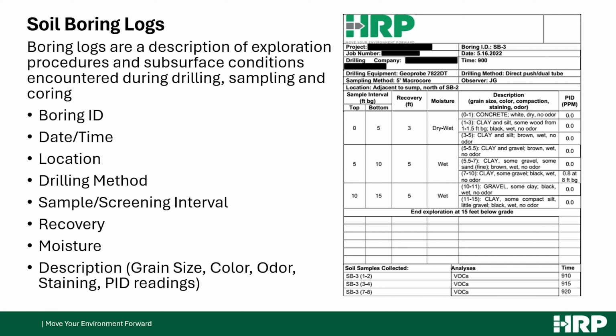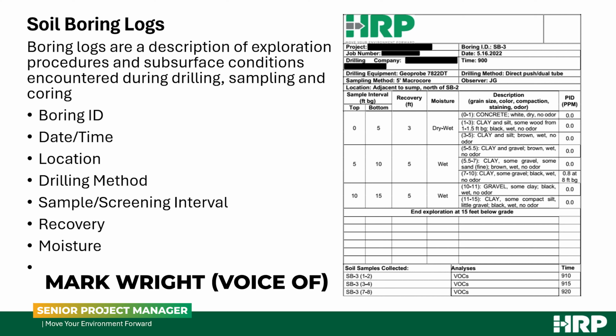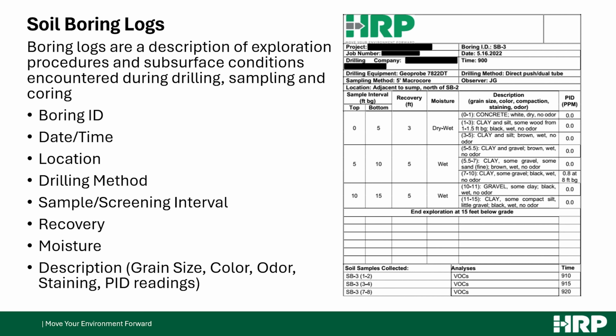I think one thing to build on that, Chris, when you are doing your soil logging, you should be making notes in addition to the description. If it is the same material that you see in SB1, if you see it again in SB3, make that note so you can start putting those units together and building that conceptual site model in your head as you're going.